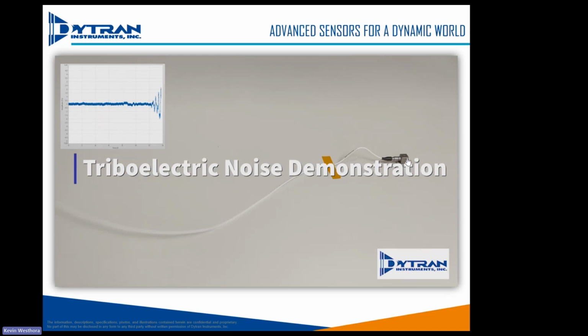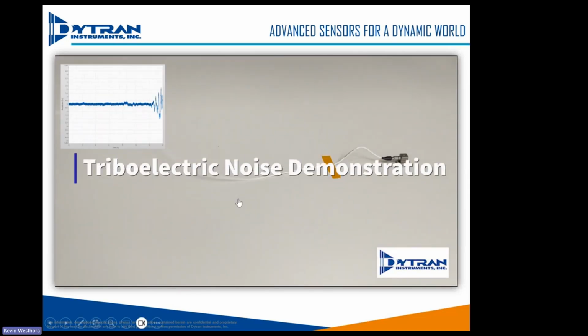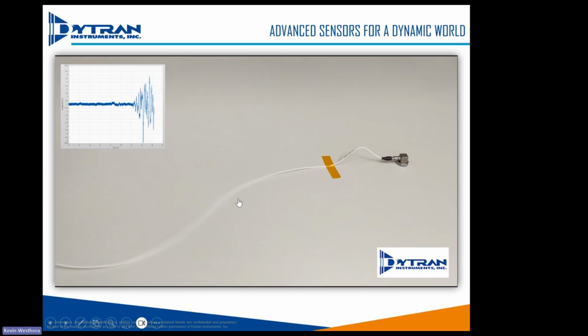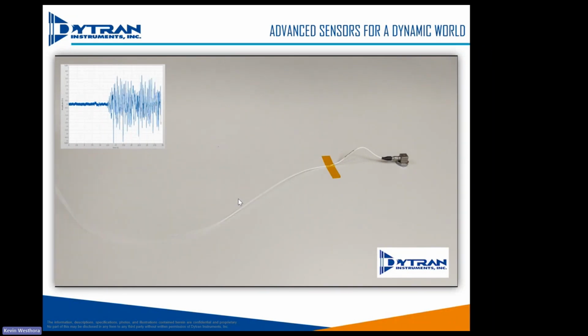This is a charge mode accelerometer with an IEPE cable. We're not going to move the accelerometer. We're just going to shake the cable. And here we go. And look at the noise that we're generating from just shaking the cable. Okay. So what's happening is dissimilar materials are rubbing against each other, building up spurious charge, and it's discharging into your data acquisition system.